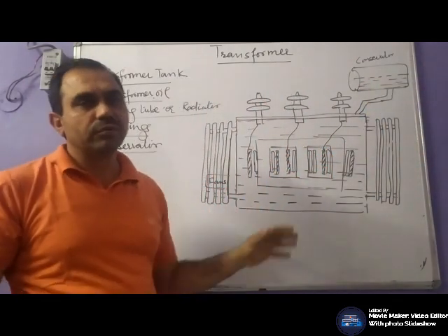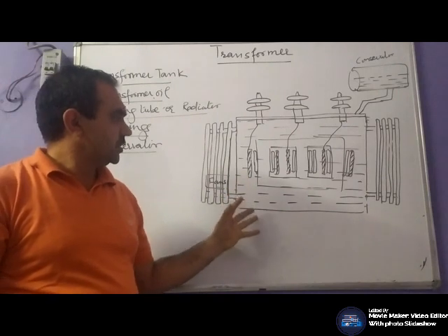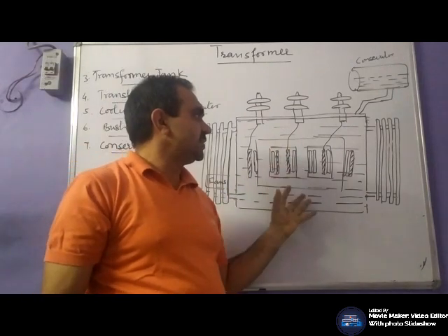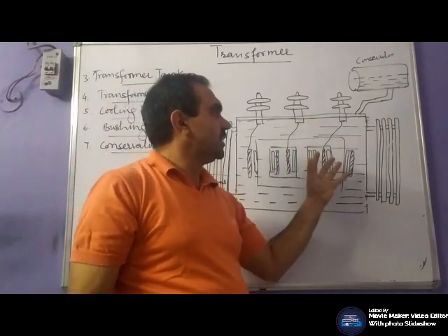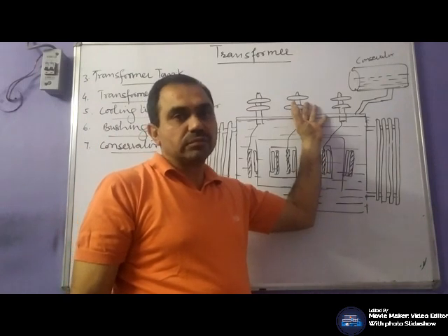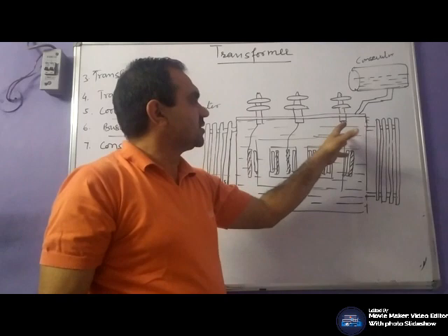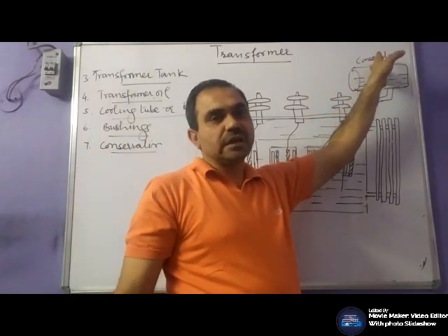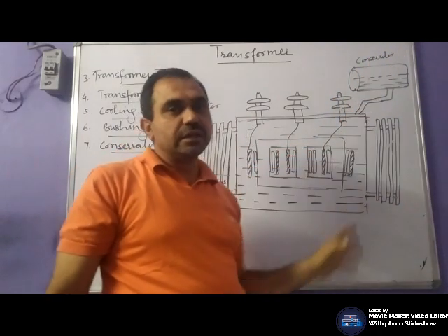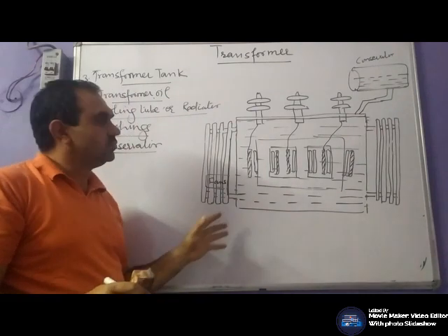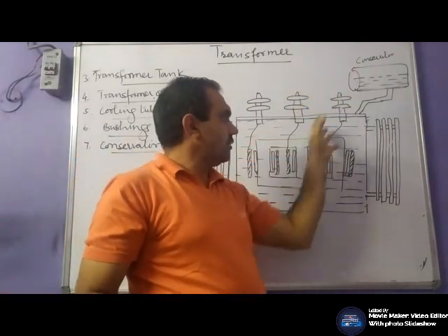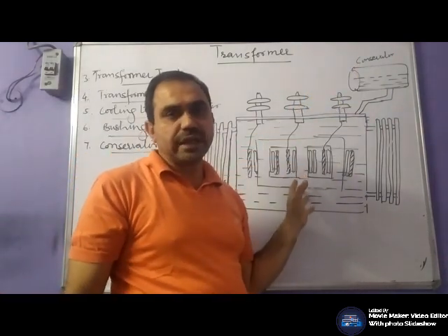When your transformer heats up, the gases expand, your oil expands and tries to come out, and the expanded oil fills up the conservator. When the transformer cools down, the oil comes back to the transformer tank.